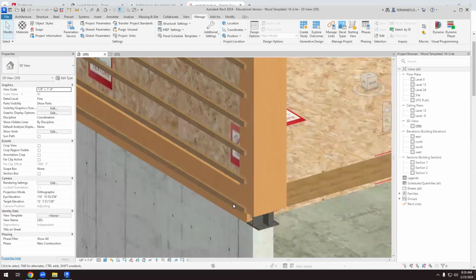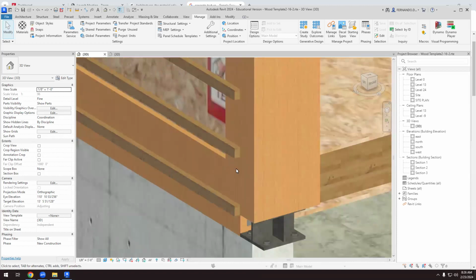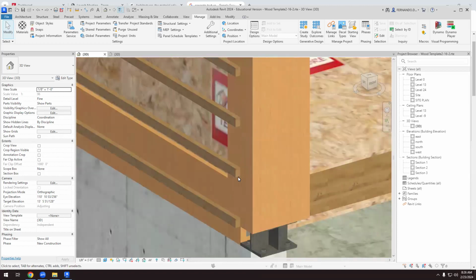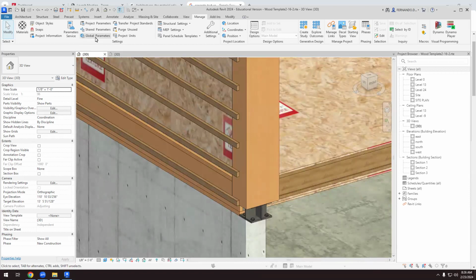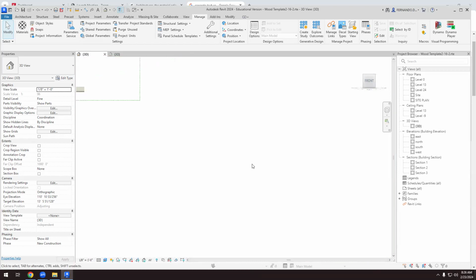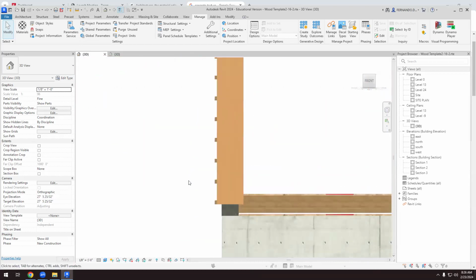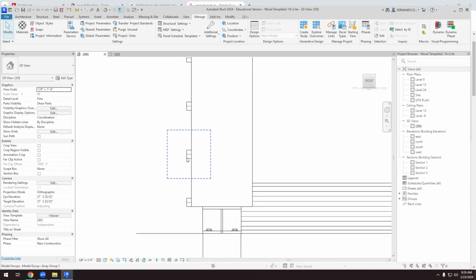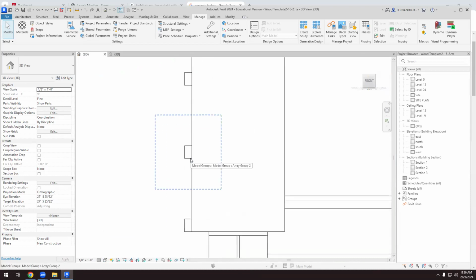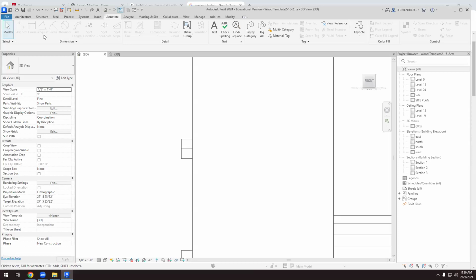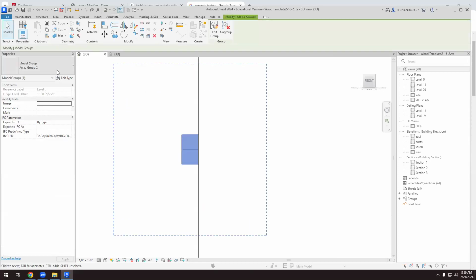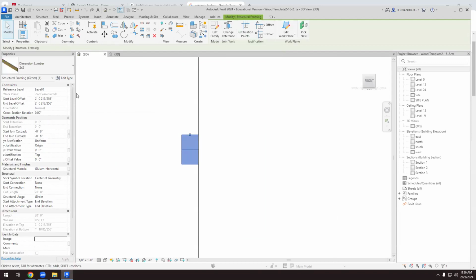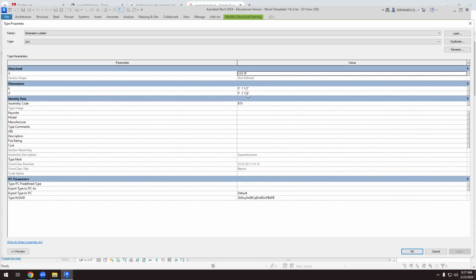So first thing, I'm going to place thermal insulation between these two horizontal elements. So let's do it. If I am in this front view, okay, I'm going to work with a hidden line. So what I want is thermal insulation here. It's a couple of inches. I think that was a 2x3 element. Group, edit type. Yeah, this is 2.5 by 1.5. Okay.